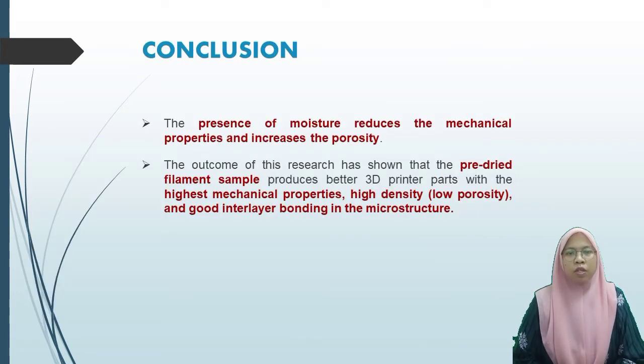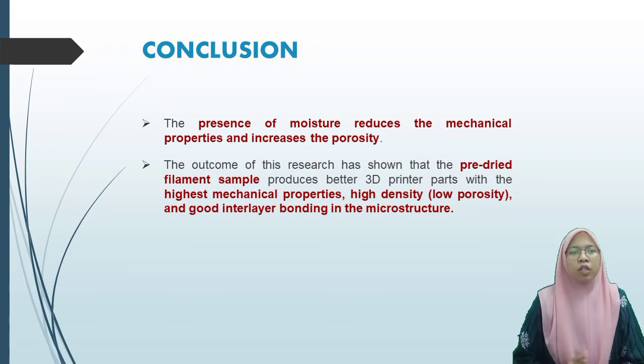As a conclusion, the presence of moisture in the filaments will reduce the mechanical properties and increase the porosity. The outcome of this research has shown that the pre-dry filament sample will produce a better 3D printed part with the highest mechanical properties, high density, and good interlayer bonding in the microstructure.